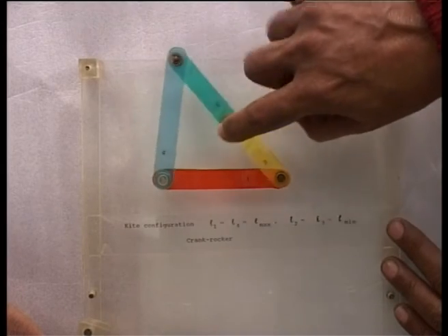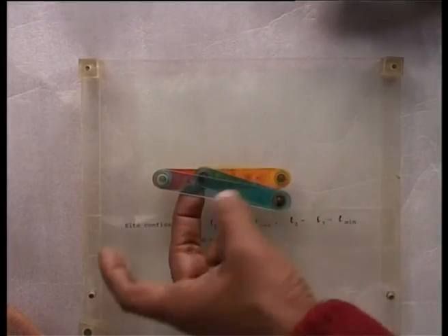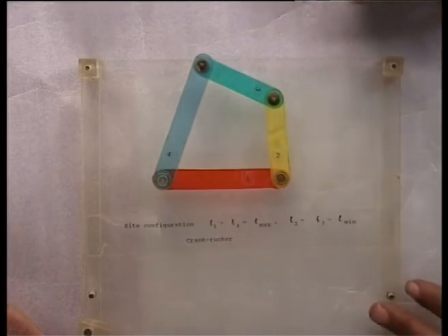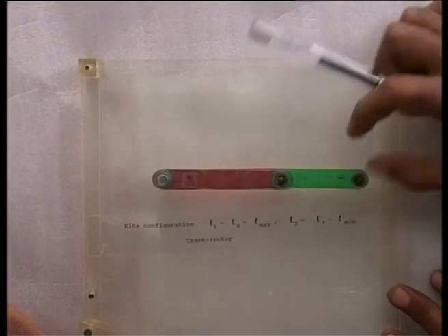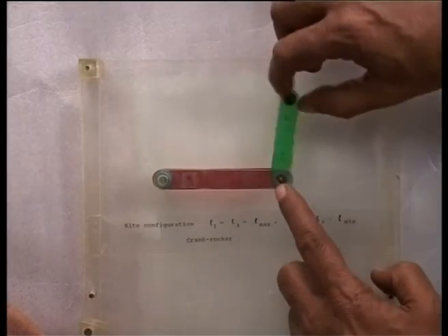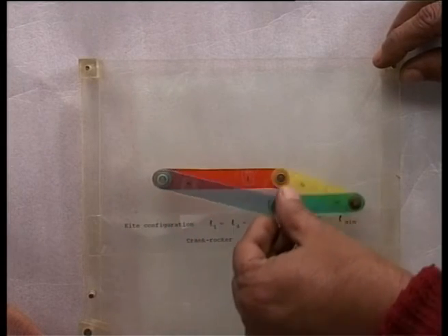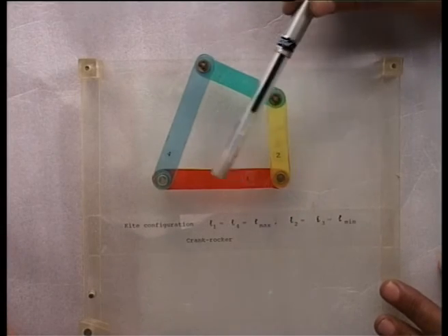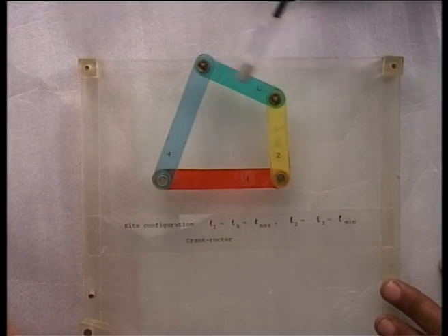As we see, we start from here, the shorter link can rotate completely, whereas the longer link is only oscillating. Here of course, because it is a transitional linkage, there will be an uncertainty configuration when all the link lengths become collinear. And here you see there is a loss of unique movement; the linkage can move like this, which is no motion transmission, or if care is taken, it can be driven as a linkage with positive motion transmission. So, here we get a crank rocker kinematic inversion with the longer link of this kite configuration held fixed. Next we will see the model from the same chain where one of the shorter links, say this link, will be held fixed.